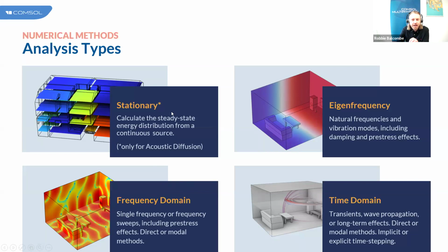And for a method called the statistical energy equation, which is available in COMSOL, we can also compute a stationary study. This will provide us with a steady state energy distribution from a continuous acoustic source. This is available only for closed acoustic problems, and it's actually a method that's used a lot in architectural acoustics. It's a very quick, lightweight way of doing an acoustic analysis.